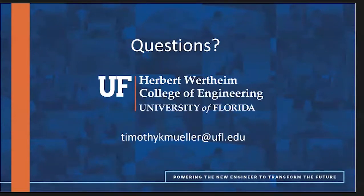And then your second question was about real wooden ties. Yeah, we have done them, and we have partnered with what was G-Rex Loram to really roll out some of those systems, and they do exist. So far, I've been pretty much in the laboratory doing this, but we do have a setup in the back. We have a trailer-mounted system that can perform this over real wooden ties. You get some issues. You're not going to quite get the resolution sometimes. Looking at like a 1 inch by 1 inch flaw out of that system, but you can get generally pretty good characteristics of a real tie.